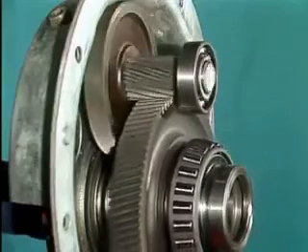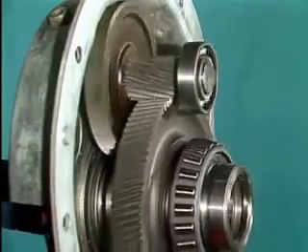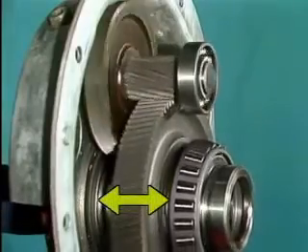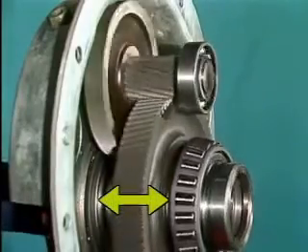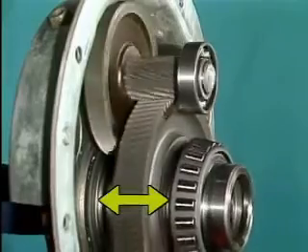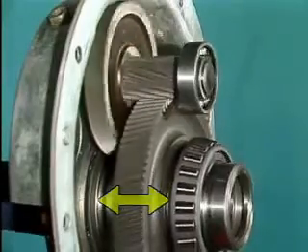Helical gears are generally preferred over spur gears for high-speed operations because they can handle greater loads and they run smoother and quieter. Unfortunately, however, there is a problem associated with helical gears that needs to be addressed when these gears are used. The problem is that as helical gear teeth mesh, an axial thrust is developed along the shafts that support the gears. In other words, the gear and shaft try to move sideways.